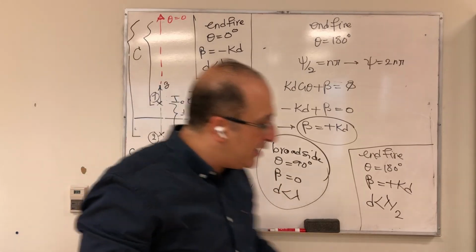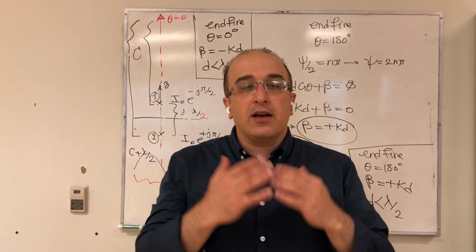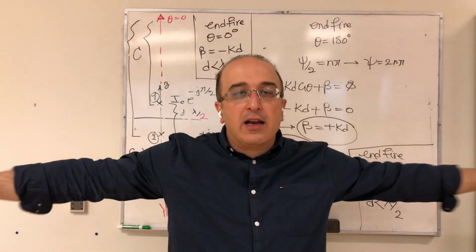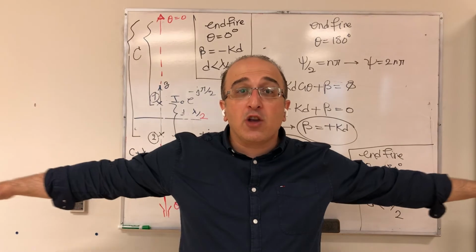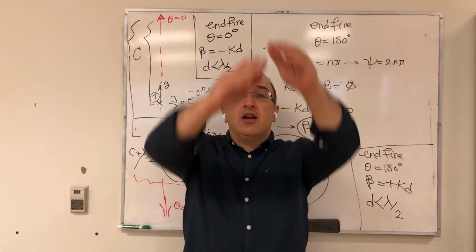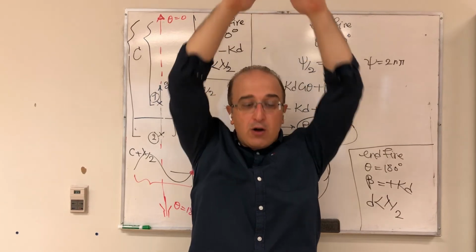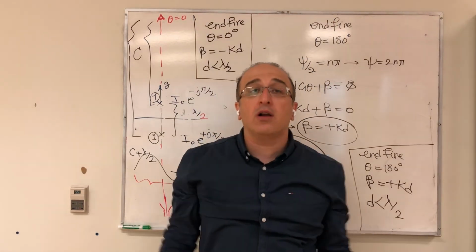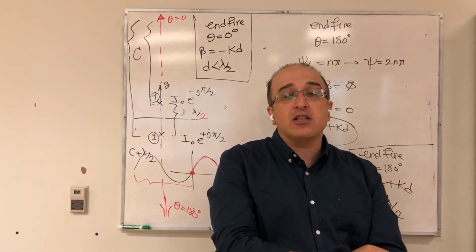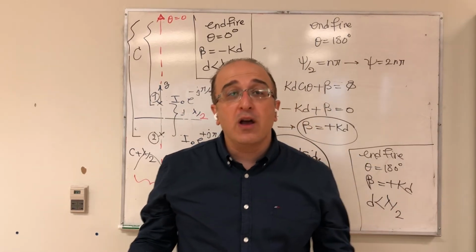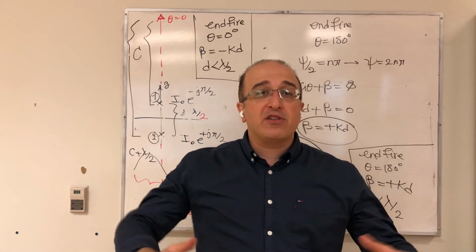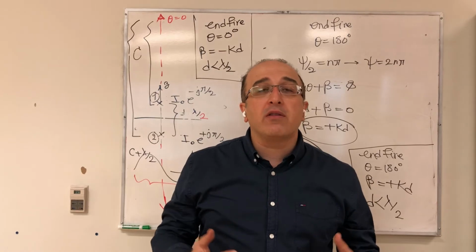So essentially, if I'm the antenna like that, and this is my main beam covering the whole plane like that, this is broadside, theta equal 90. Whereas for end fire, you are essentially looking up, theta equal 0, or looking down, theta equal 180 here. Now, for the next discussion, we're going to take a look into phased array antenna, which can have, for example, an arbitrary theta. Let's say theta equal 30 main beam.